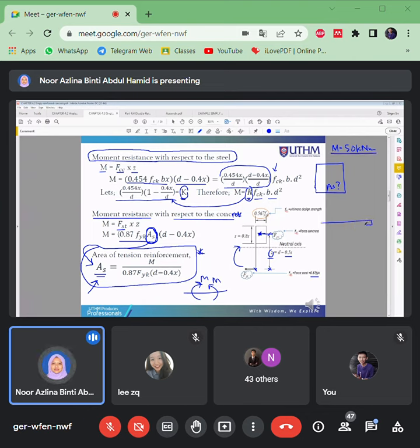It's from the beams. Let's say these beams have to support the load, might be from the slabs, might be from the brick wall or from the concrete slabs, which is in kilonewton per meter. Once you calculate the reactions, you will come out with the bending moment diagram and shear force diagram.